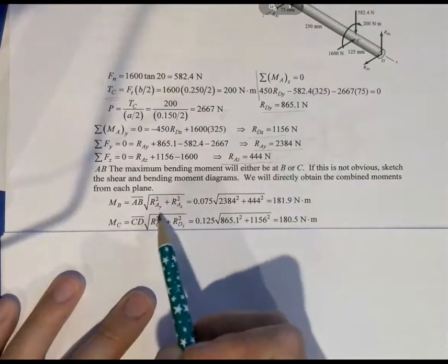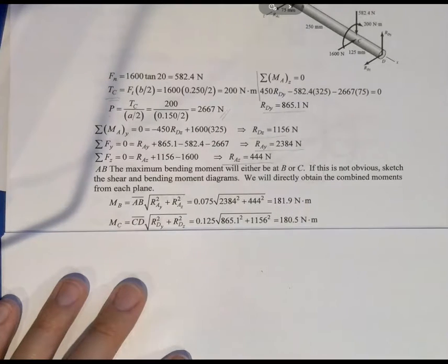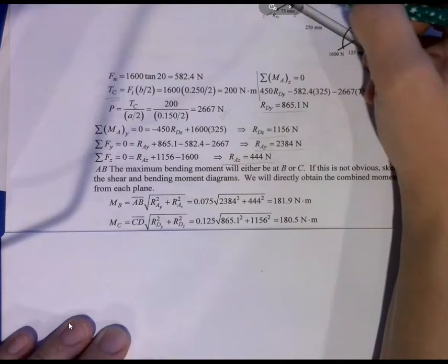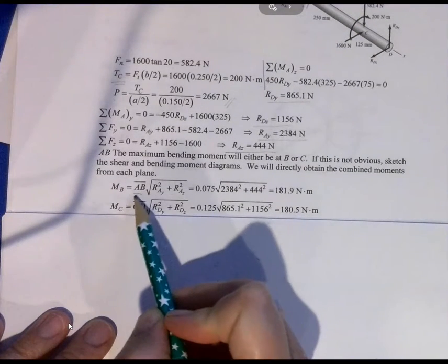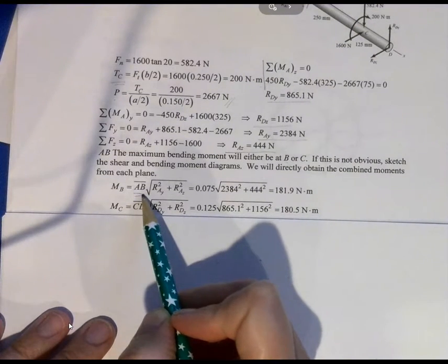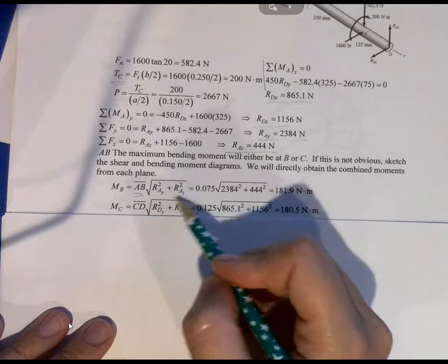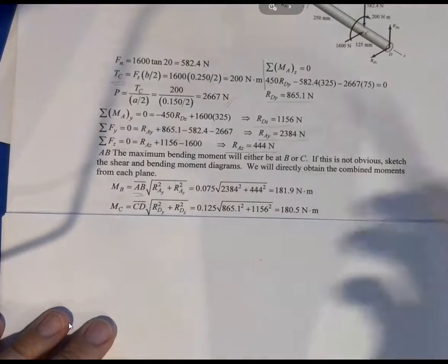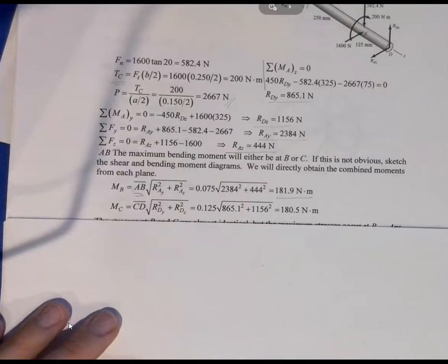But instead, the bending moment at B, and this is assuming we're looking towards A, so we've cut the bar at B, and we're looking towards A. The bending moment is simply the length of the bar, the axle from A to B, times the resultant vector at R, which necessarily is perpendicular to the bar axle. And so we get a magnitude for the bending moment at B, and same idea, right?